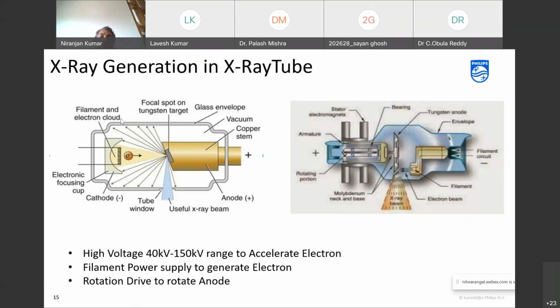That's why we say the X-ray tube or this insert has to be vacuum to a level where more than 99% of electrons can travel from the cathode freely. And the moment it is vacuum, the remaining 1% gas also has to be in inert form. We cannot have 1% oxygen or some kind of moisture, right?